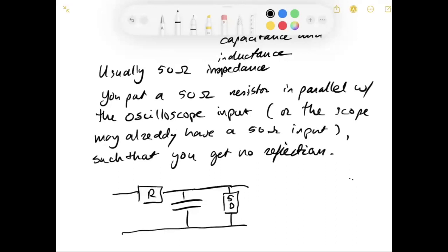And designing circuits for higher frequencies means that you need to start including these kind of considerations. So the long story short, the way we've been doing filters is kind of the intermediate AC frequency circuits. For higher frequency circuits, that's not realistic because you cannot get a clean signal delivered to a high input impedance with a cable, because the cable, once it has a certain length, it's going to cause reflections.